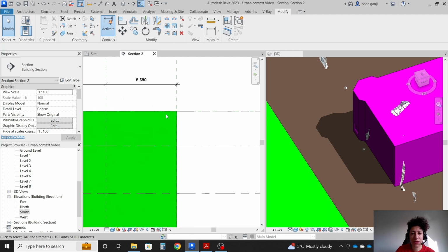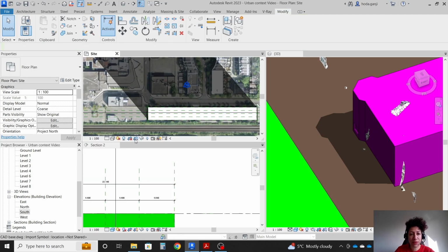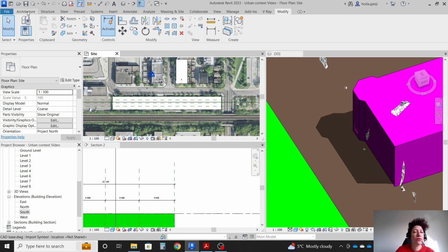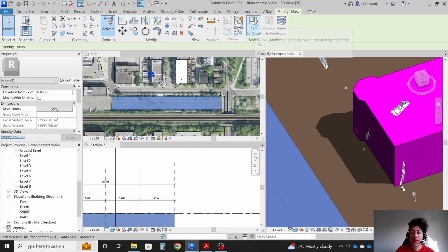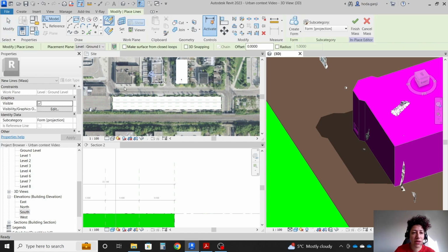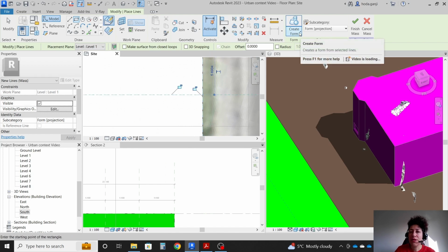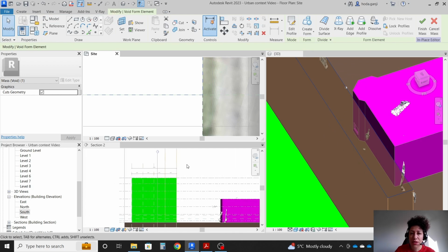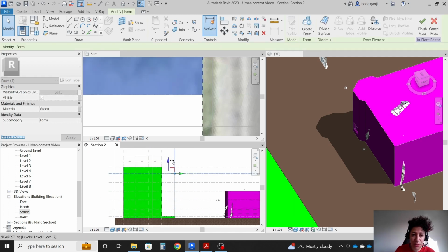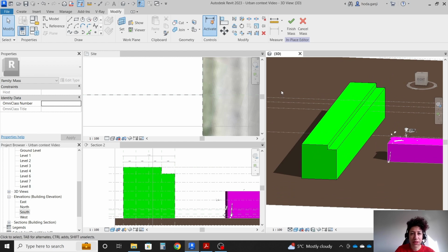And here on this last side, I want to say that on this last span, maybe we don't want to have a floor on our highest level of the building. So I want to go here. How about I bring my site plan as well, WT, and I want to create another void. Let's remove the shadows. I'm going to go with selecting this mass, the green one, edit in place, and we want to go with one rectangle here from this corner to here, and I'm gonna say turn it into a void form. And let's see, now it goes down. I'm gonna select this, move this up till here. So what happened is that we consider that here is not going to have a level.